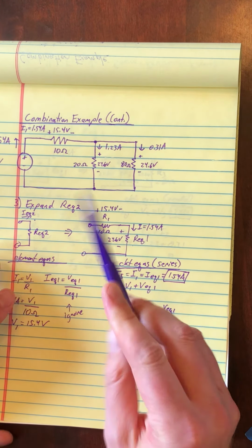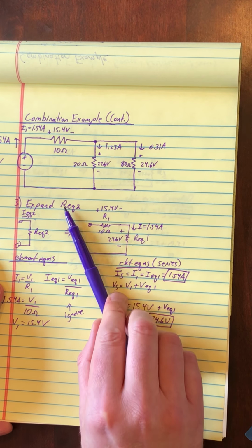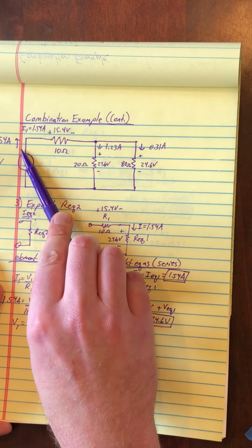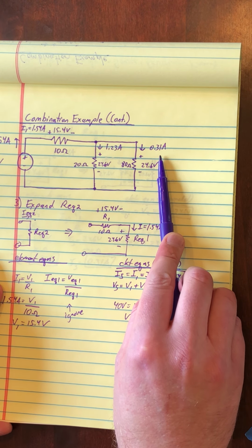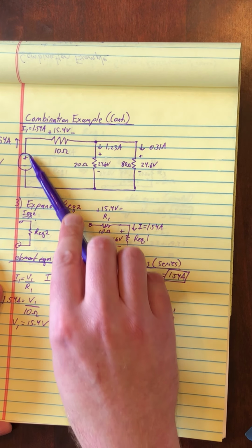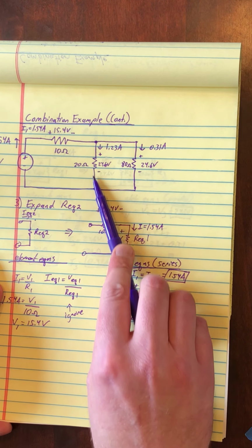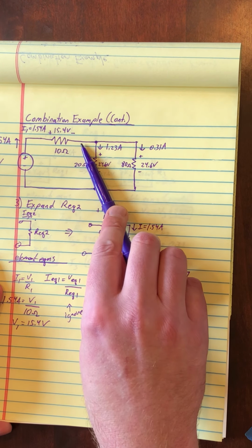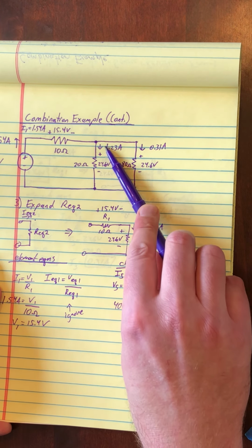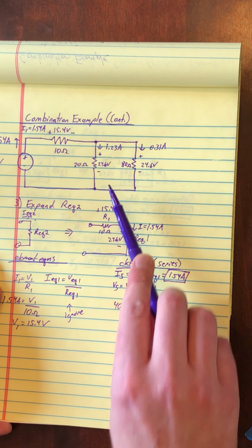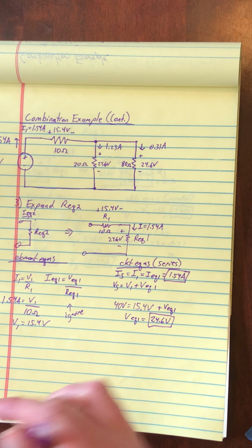And so we can do a quick check with Kirchhoff's laws if you wanted to. So flow in is 1.54, flow out 1.23 plus 0.31, that is 1.54. And any loop, 40 volts, 15.4 drop, another 24.6, 15.4, another 24.6, both add up to 40. 24.6 and 24.6, they're the same. So that looks like a good solution.